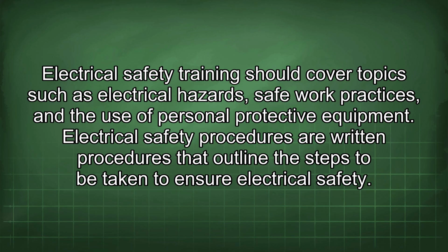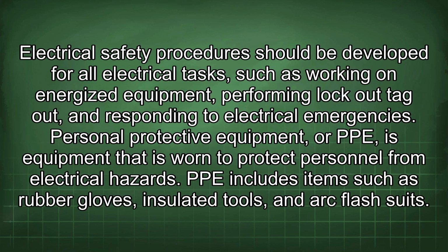Electrical safety training should cover topics such as electrical hazards, safe work practices, and the use of personal protective equipment. Electrical safety procedures are written procedures that outline the steps to be taken to ensure electrical safety. Electrical safety procedures should be developed for all electrical tasks, such as working on energized equipment, performing lockout-tagout, and responding to electrical emergencies.